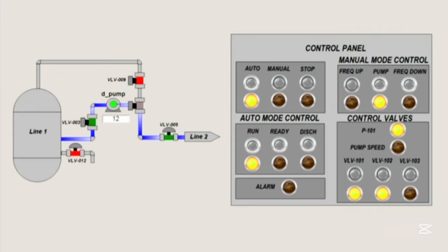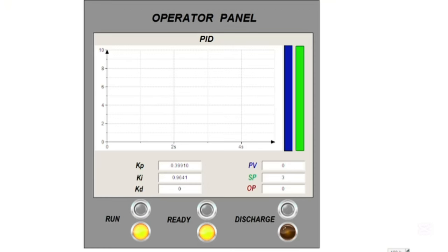It continuously tracks the pressure value and displays alarms and system states in real time, making it easy to monitor the entire operation. In addition to this, we integrated a PID controller into the M241. The PID loop now regulates the system based on the input signals from the pressure transmitter, ensuring smoother control and automatically maintaining the required operating range.